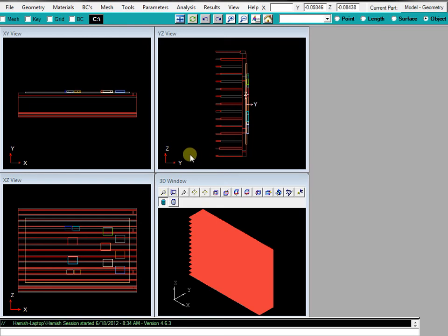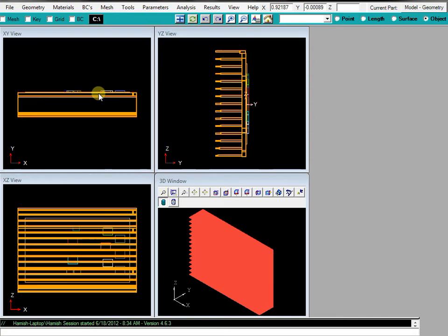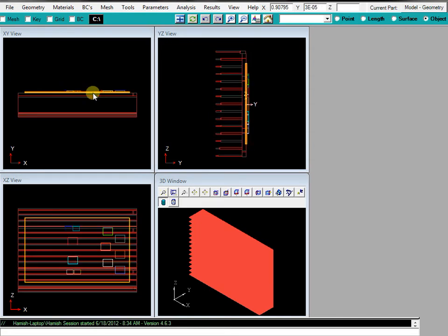Now that we've imported our geometry, we're going to go ahead and make some modifications. The first modification: when I brought the PCB in, I actually brought it in with FR4, but in this case, it's a force of habit, we're going to be using a metal PCB. So it's going to use a copper substrate, so the majority of it will be copper with a 0.1 millimeter dielectric layer on top, and then traces on top of that.